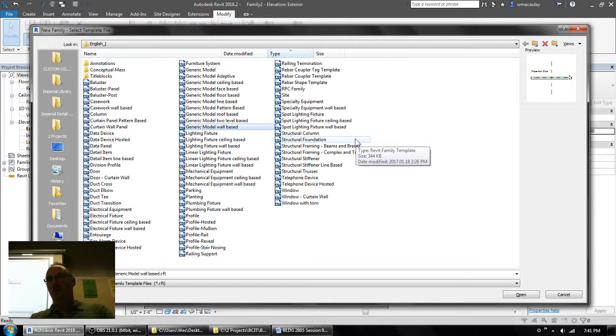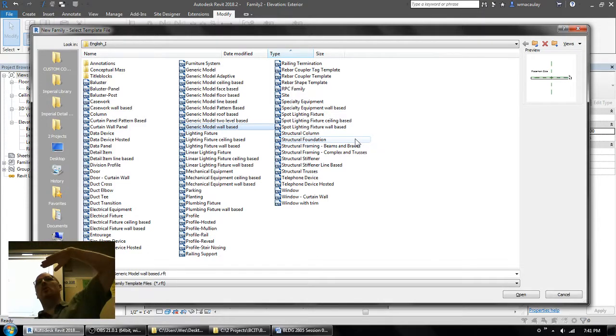If any of you are working on a project in the future where you have a sloped wall, or a wall that's going to be maybe partly a roof, the standard window family, if you were to put a window into a sloped wall, that window would still put itself in vertically, which is kind of infuriating. Windows do not follow the angle of a wall. The regular windows don't anyway.